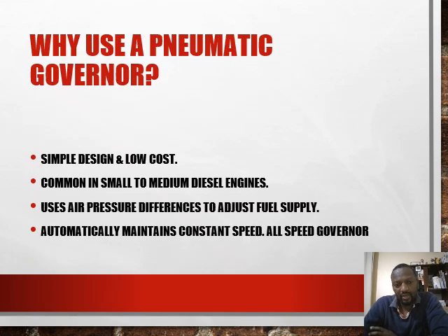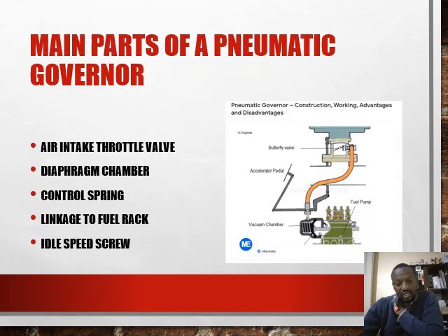So then why use a pneumatic governor? One is that it is simple in design and low cost. It's a very small unit, as we're going to see much later. And two is that it's common in small to medium diesel engines, and it uses a pressure difference to adjust fuel supply. So it is fully automatic and depends on the pressure generated at the engine. And lastly, it will automatically maintain engine speed.